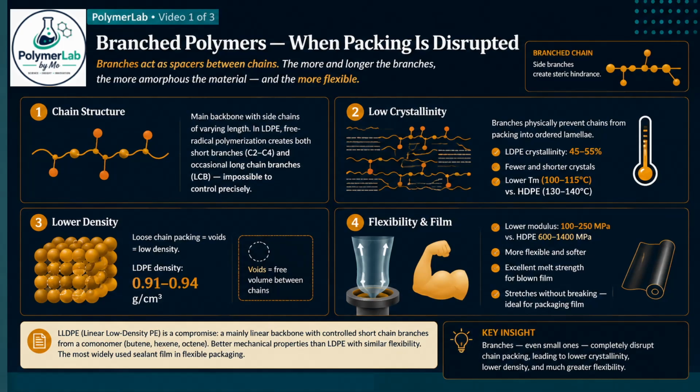Now branched polymers. The key insight is that branches, even small ones, completely disrupt the ability of chains to pack together. In LDPE, free radical polymerization at high pressure and temperature creates a random distribution of branches, some short, 2 to 4 carbons, some long. The process is difficult to control. You get a broad distribution of branch lengths and positions, and this randomness is what makes LDPE so different from HDPE.